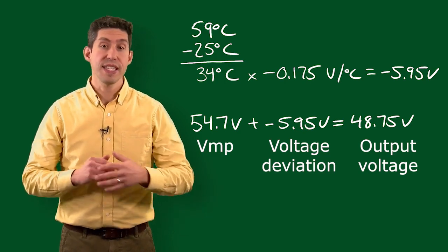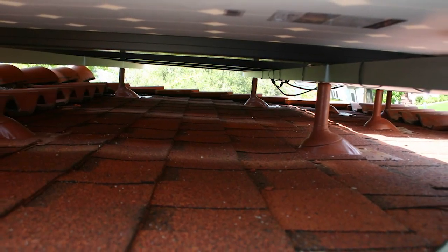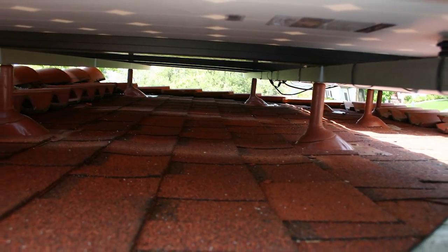When considering the voltage under warm weather conditions, 30 degrees Celsius is not always the best value to choose when designing system temperatures. Deviations from that value will be based upon empirical data that you can find online for temperatures and combining that with the National Electric Code or other sources. Suffice to say, the further away from the rooftop, the lower the temperature adder will be. We'll come back to this again when we do site-based design in the next course.